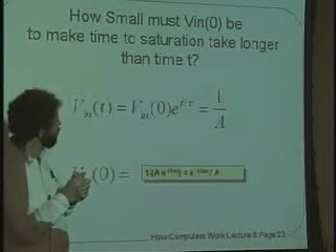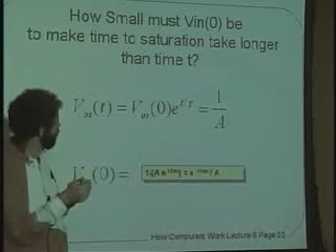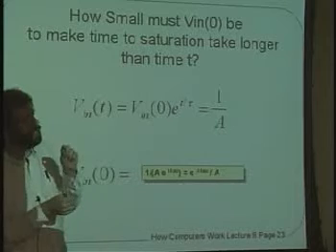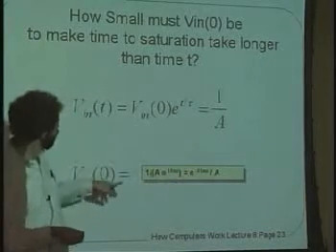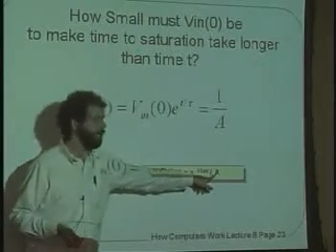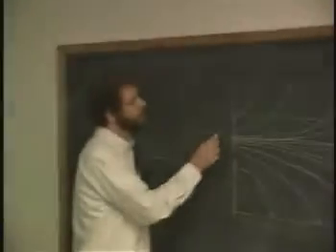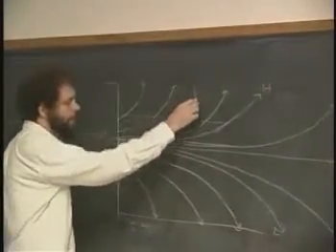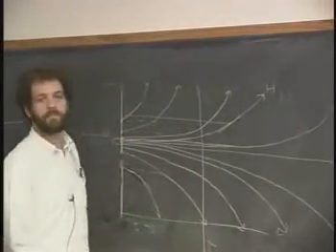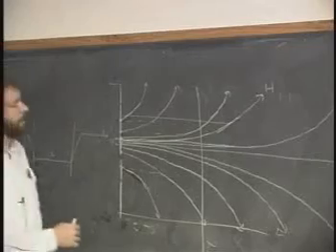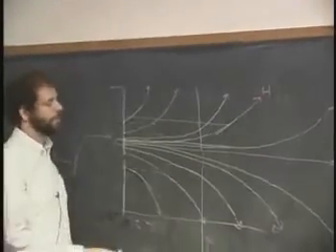And when you work out the math of this, what you discover is that the probability that you will stay in a metastable state for a time t is equal to e to the minus t over tau divided by a. And what that means is that I'm going to ask the following question. Let's say that I decide that I want all metastability to be over by time t here. In other words, I want all of the metastability to be done by this time.